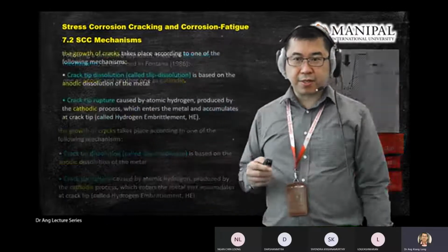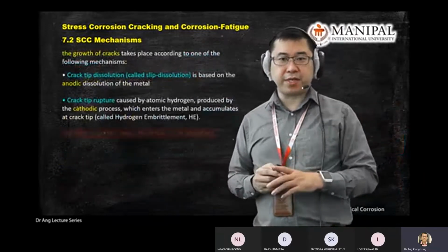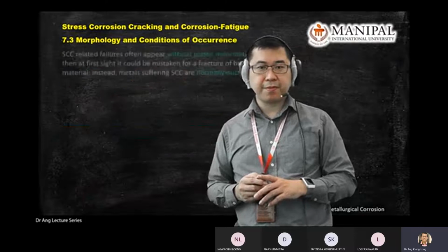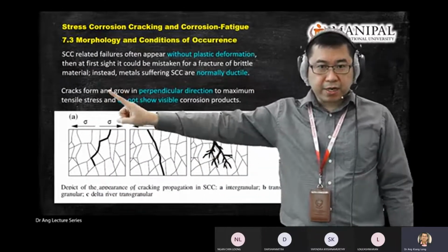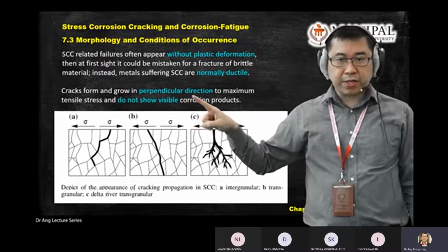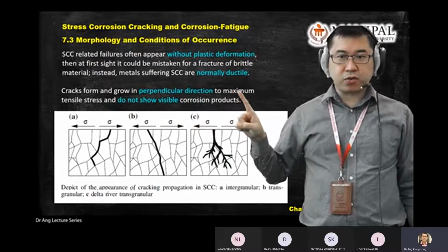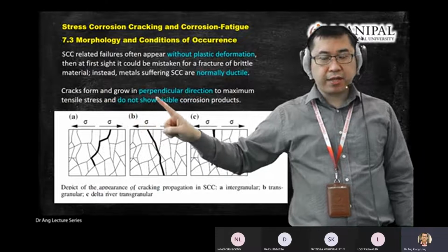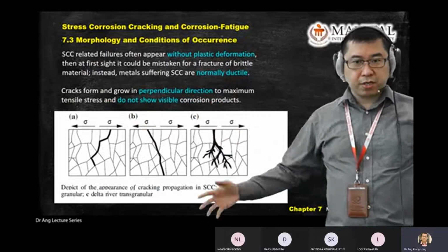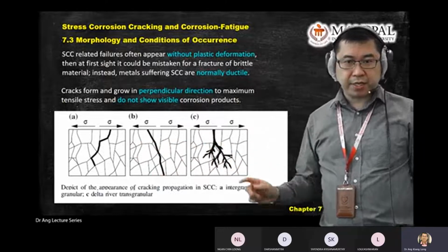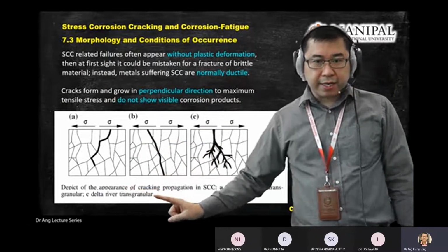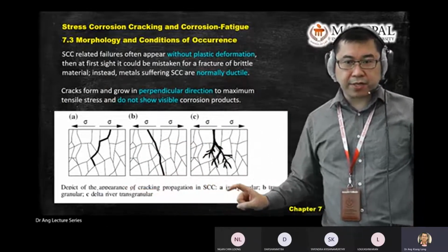That is the way you explain SCC. Again, crack growth is in the perpendicular direction, or 90 degrees, to the maximum stress and does not show any products.